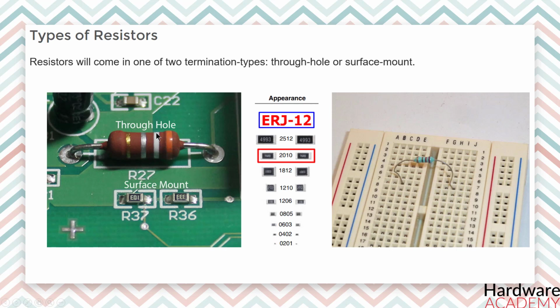We could talk a lot about why someone should use through-hole instead of SMT. Well, overall, through-hole components can withstand more environmental stress, and that's the reason why through-hole technology is commonly used in military and aerospace products that may experience extreme acceleration, collisions, or high temperatures, right? Also, the through-hole resistors, since they are bigger in size, can usually withstand more current than their SMD counterparts. The key difference between SMT and through-hole mounting is that SMT does not require holes to be drilled through a PCB, and SMT components are much smaller and can be mounted on both sides of the board.